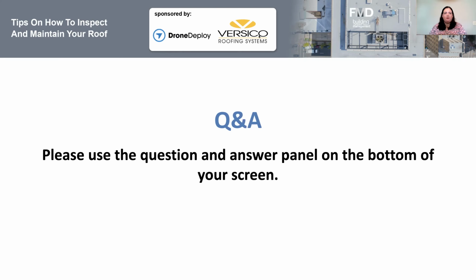Great, thank you both. We have a question on, do you need to remove HVAC units to re-roof a low slope roof, Chris? Not necessarily remove. A lot of times we have to have them lifted. If it's a re-roof and the existing roof is staying and you're adding additional insulation to get your R-value up to code, that starts to limit your flashing heights.